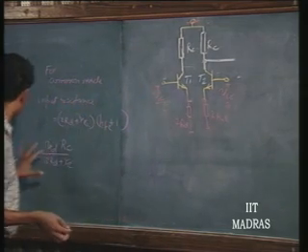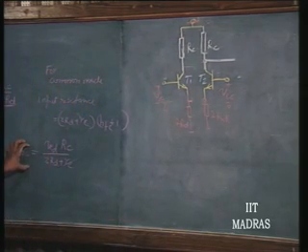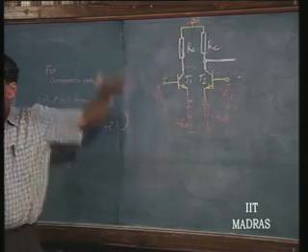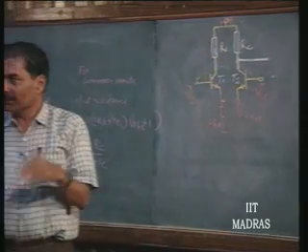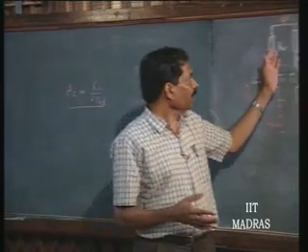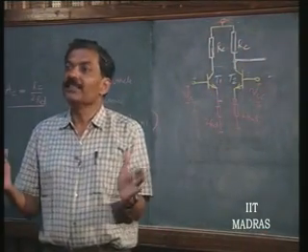If VOC itself is very small compared to the differential output due to differential mode signal, then making this equal and getting it cancelled is an easy affair.